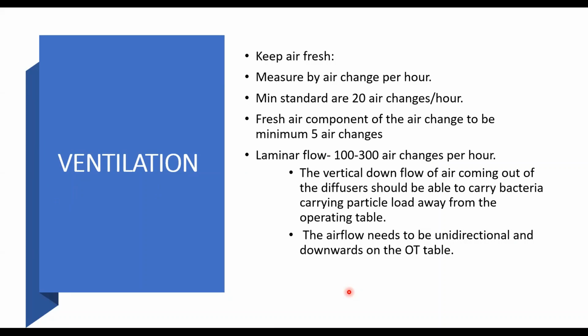The airflow must be laminar flow, which gives about 100 to 300 air changes per hour, and usually the airflow is from top to bottom onto the operating table, so as to carry bacteria-carrying particle load away from the operating table.